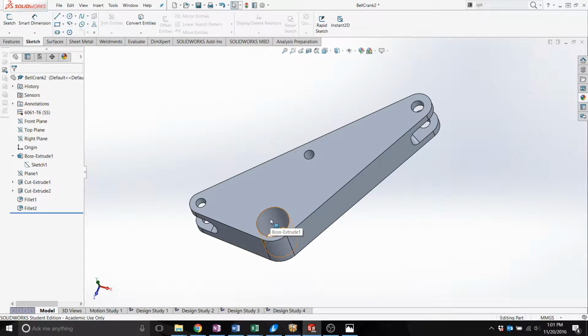And then there's a bearing in here, a bolt with a force on it, another bolt, and a secondary feature that is bolted to the bell crank as well. The important thing to know before importing this part directly into Inspire is that Inspire has two cases for volumes. They have a design space and a non-design space. Design space is where the optimization actually occurs and the volume is changed, and the non-design space is where the forces and constraints are applied and no optimization happens there.